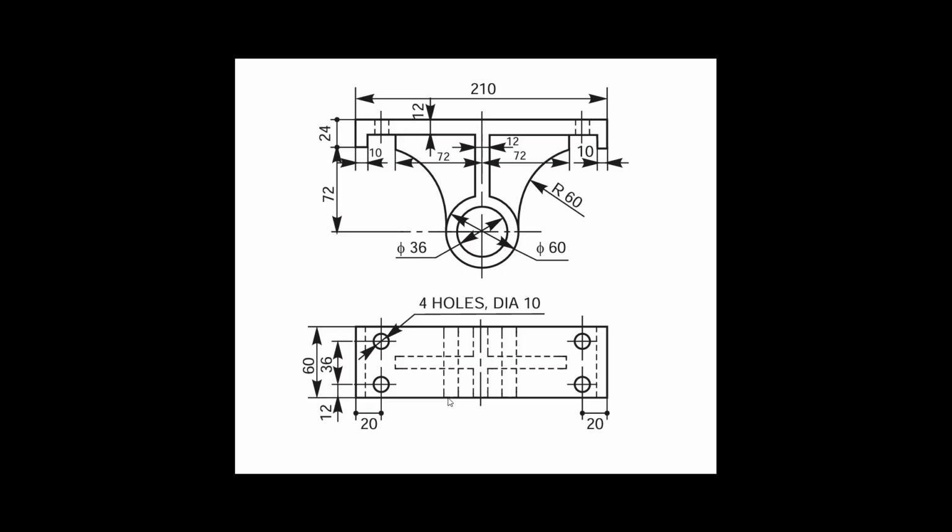That outer circular edge is represented like two opposite vertical hidden lines. That inner circular edge is represented like this formation, that is smaller hidden lines. Both are not visible in the top section view also. That's why they are represented like hidden lines. Also, the two sharp edges on the outer zone are also represented like hidden lines.